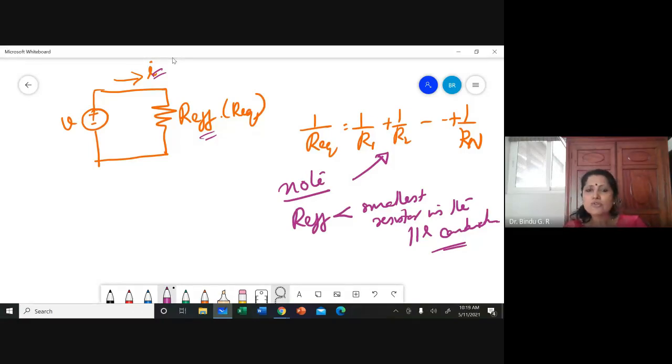One way is to add one more small resistor in parallel, so that the effective resistance goes down by a lot. This is a very important point to note, because there are cases where you will have to reduce the already existing resistance. You could have brought in a series resistance or changed the whole arrangement with a resistance lesser than the previous value.